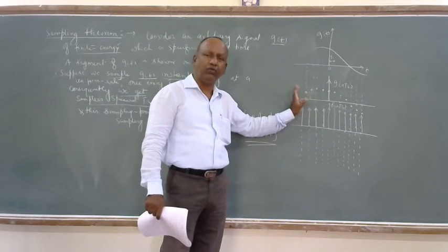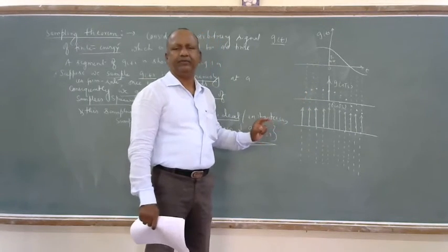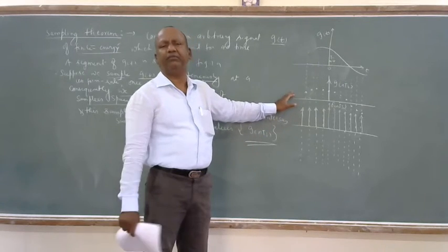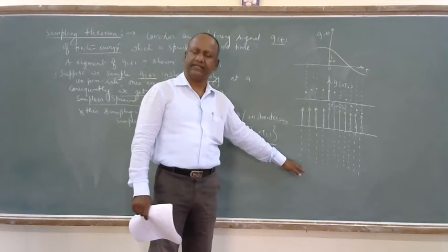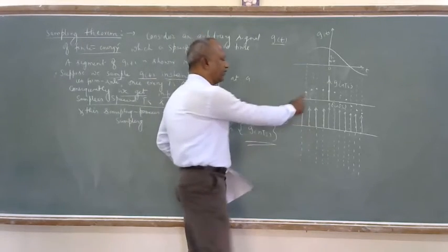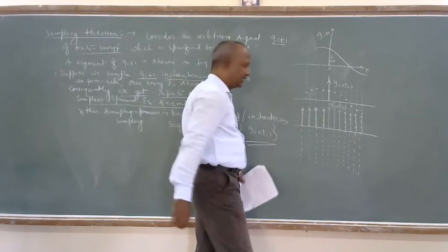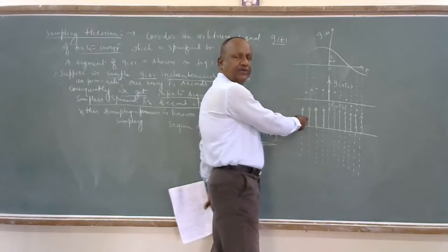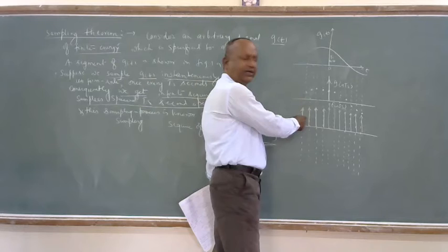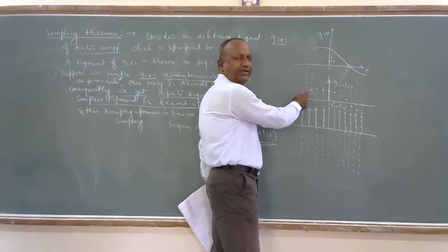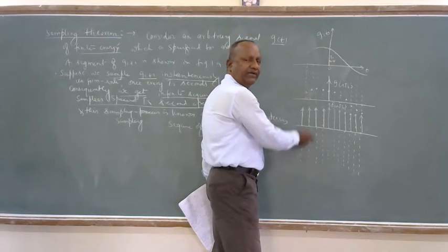Now it is only a number or a value. But in my communication system, that number is not going to work. So it should be present in the form of what? A signal or a function. That's why, to convert that value into a function or a signal, I am using the sequence of Dirac delta functions. You know that the area under this function is equal to 1 into this value itself, but it is going to be available in the form of a delta function.